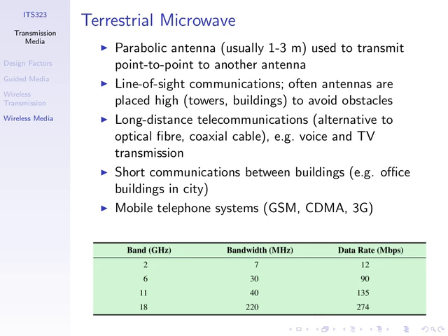So the signals pass through some obstacles, but when the signal hits an obstacle, it attenuates. It gets very, very weak. So if there's a tree in the way, then the signal will be attenuated by that tree, but it still may be successfully received. We just need to increase the transmit power. If there are many trees or a large building in the way, then the signal will not pass through, or what comes out the other side will be so weak that the receiver will not be able to understand.